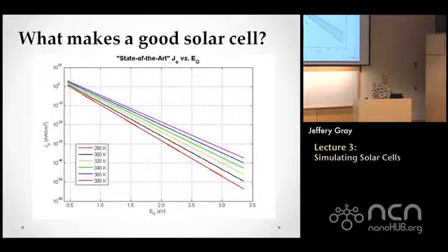And of course, if we're putting these solar cells in a power plant, we're subject to the whims of Mother Nature. On a day like today outside, even at ambient temperature, they're going to be operating at a much higher than room temperature, and they absorb energy as well and heat up in the sun, so they can get very hot. And you can see what happens as the temperature increases: the leakage current increases, and therefore the voltage goes down.